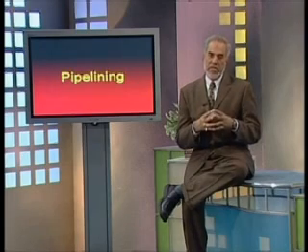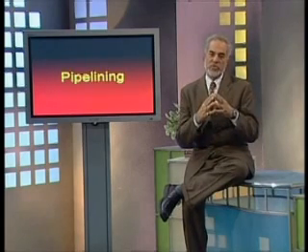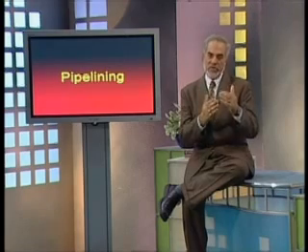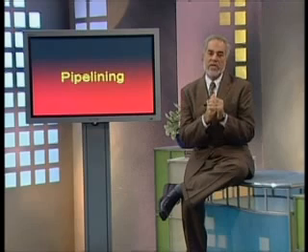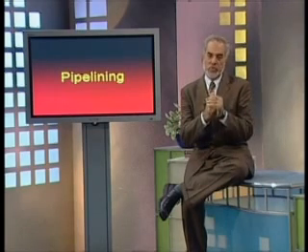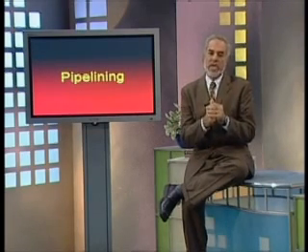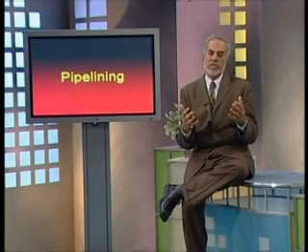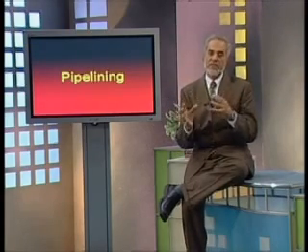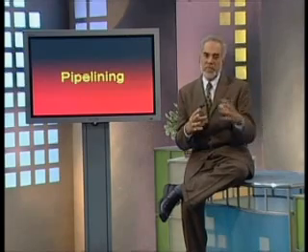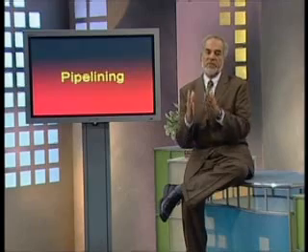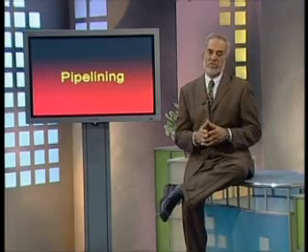Through the pipeline, we have the execution in different phases. Different instructions are simultaneously executed, and that gives a better throughput. As an example, if we have one instruction which needs to fetch data from the memory and it would take some time, simultaneously the next instruction would come into the pipeline, and in the pipeline we could have simultaneously 5 instructions at different stages of execution.